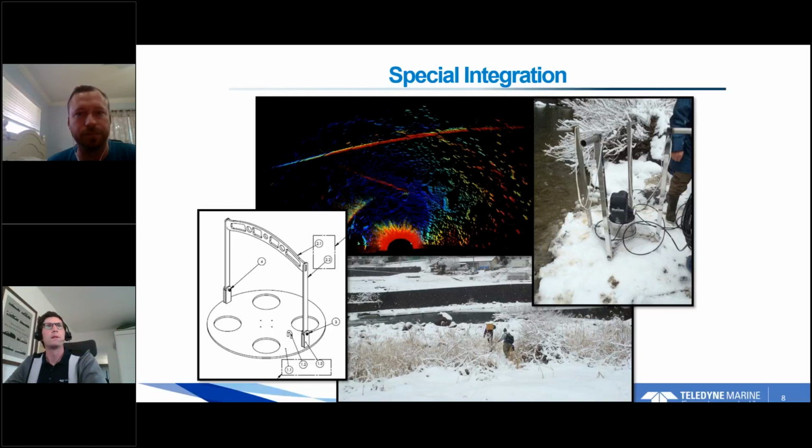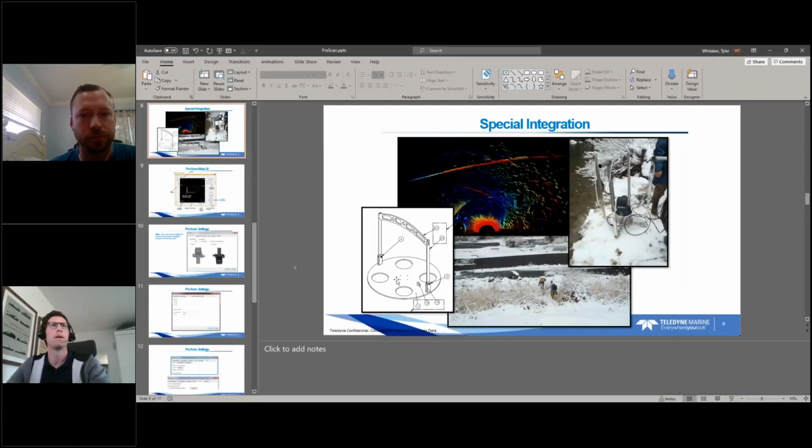So we went over this last week. John, you were on this, right? That's right. You deployed in a very shallow river in Japan. They were looking for scouring along this structure here, this wall. They used this kind of custom tripod to get the sonar nice and low. Again, it was maybe 2 feet deep or less, something like that.